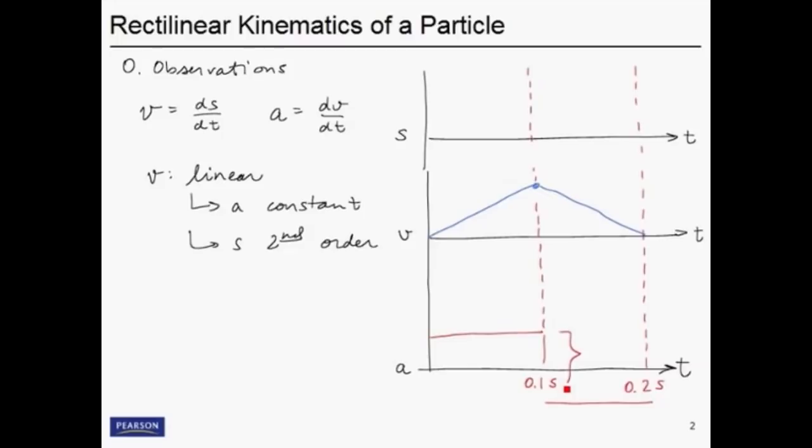It's kind of skew symmetric with respect to that center line at 0.1 seconds. Now, the S-curve is a little bit harder to visualize, and you may or may not be able to see this, but because of the nature of this, we know that there's going to be sort of an inflection point on S because V changes slope. We know there's an inflection point sort of here at point 1, and up to that point, the curvature is going to be concave up, and after that point, the curvature is going to be somehow concave down. So I didn't draw that exactly smoothly like I wanted to, but you get the idea of what's going on here. And we know from the problem statement that this is going to be S equals 0.5 meters.